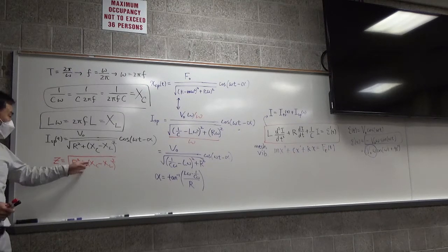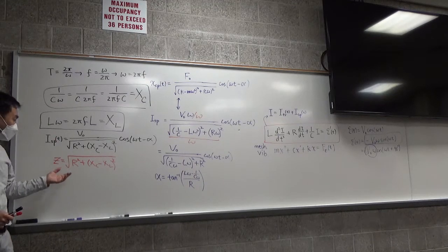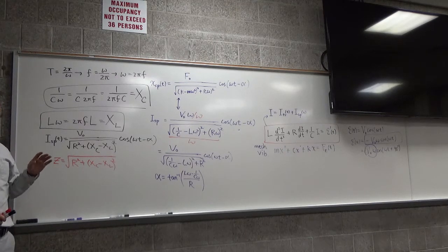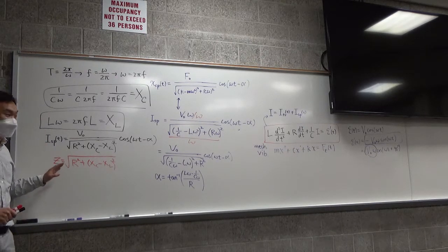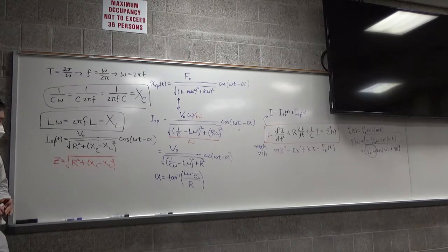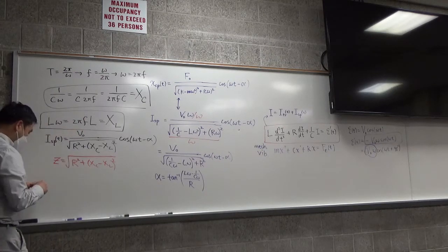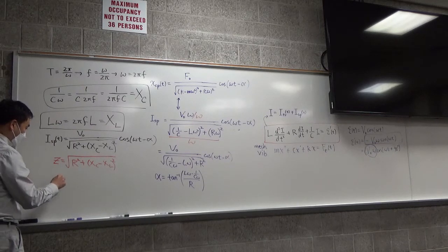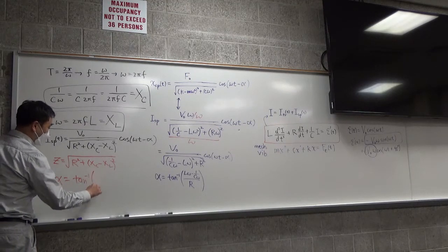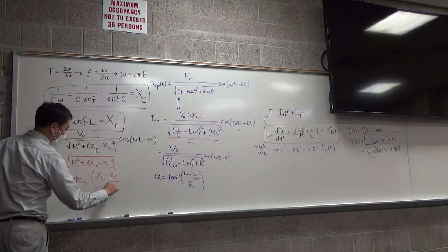All these things are there, and it tries to use this phase diagram to show you why you end up with something like a Pythagorean theorem. And that will actually make more sense now that you can have confidence that this is indeed what is happening. And by the way, this formula here would be alpha equals tangent inverse of XL minus XC over R.